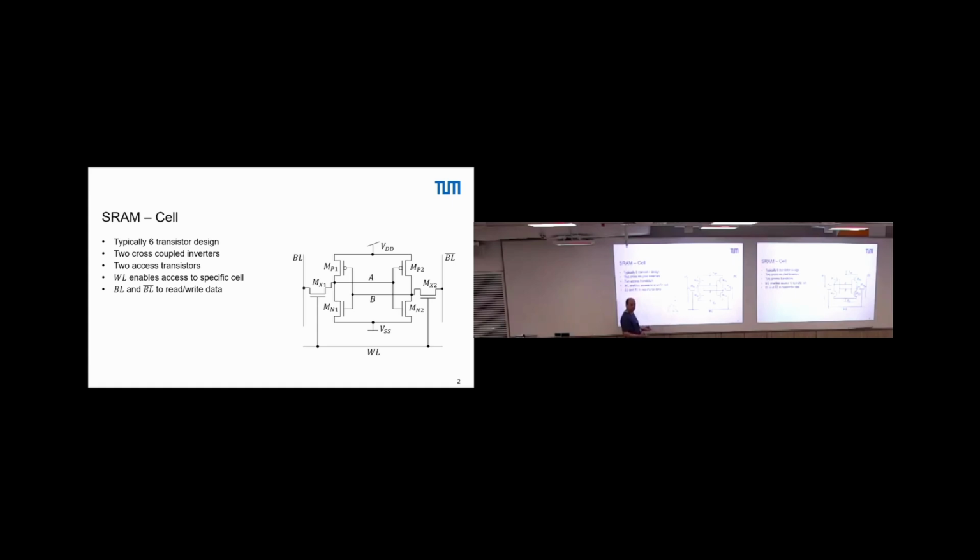Since we have an analog circuit at the end, we don't just go down to 0, but it is some smooth operation. So we have some transition from VDD to ground, and at some point, which corresponds to the threshold voltage of the NMOS, we are in saturation with the NMOS, the PMOS closes, and we are at 0, right?